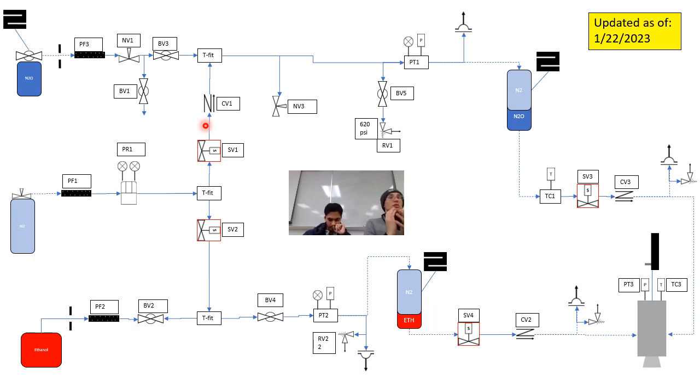In general, we are very hopeful that pressure increases, and maybe a temperature measurement increases, and thrust is measured. If those things are not measured, especially if none of those things are measured, we have a very big problem because we're flooding our engine, and there might be a sparkler still trying to cause an explosion, which would be a hard start, a large pressure increase, and it could break things.